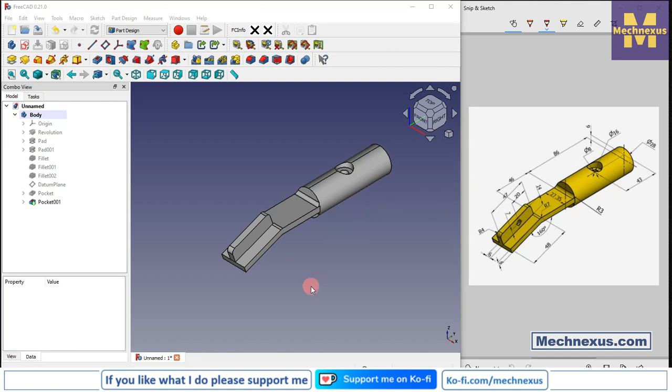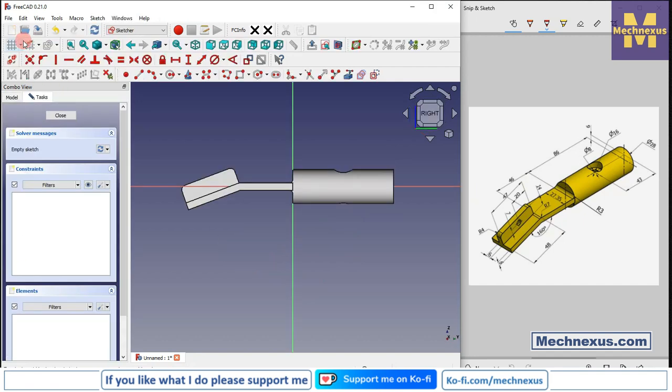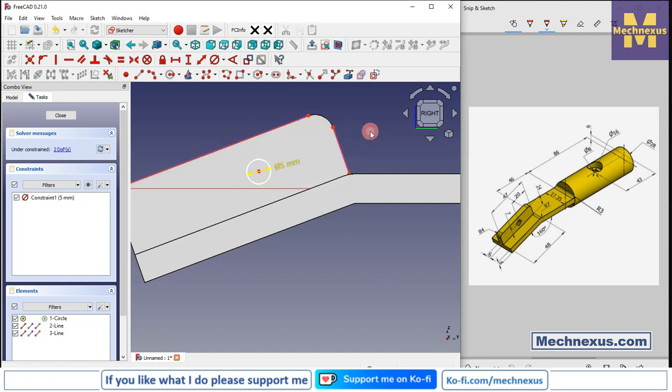Now we will create our last feature, which is this hole. So we will select this face and click on the sketch, and we will click on the project geometry, select these two and click on the circle, create a circle and provide it a diameter of 5 mm